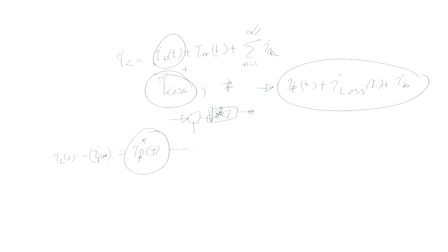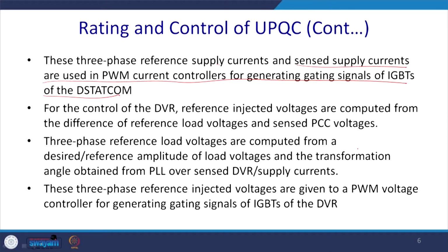So, generally it is compared in ABC with what actually you are injecting, and that you feed to the PI controller, then you have a PWM block and that has a switch. So, for the one leg, similarly, we have 3 such pulses. So, generally it is unipolar in nature for the 2 level inverter, and accordingly for the multi level inverter we have a multi level switching scheme.